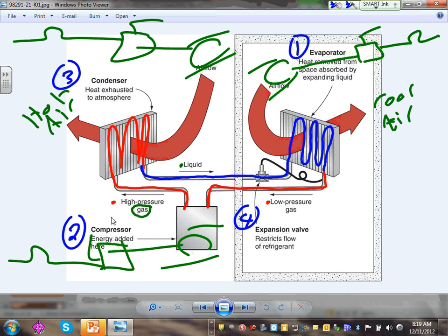So can I get you guys to give me a thumbs up if you understand that bigger systems use water? Smaller systems, refrigerant, not a big deal. Bigger systems, they use refrigerant to chill the water and they circulate the water. They still use refrigerant, but instead of throwing the air right through the refrigerant to get the cold air, they use the refrigerant to chill water, and then they carry the chilled water all the way to different parts of the building in different air handling units, and then they blow the air right through that chilled water to get you the cold.